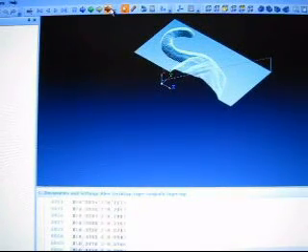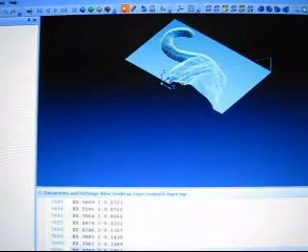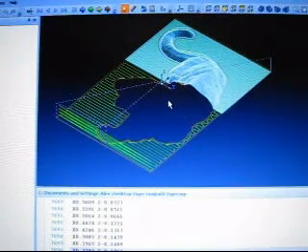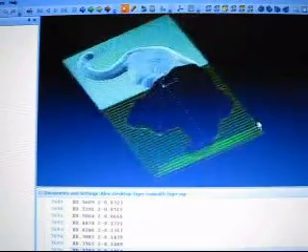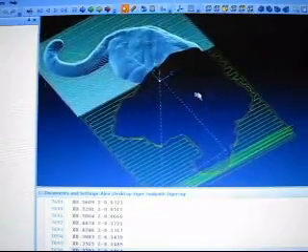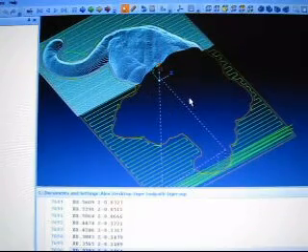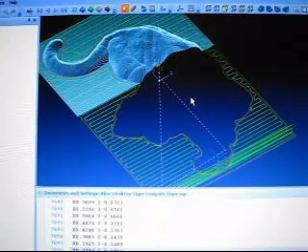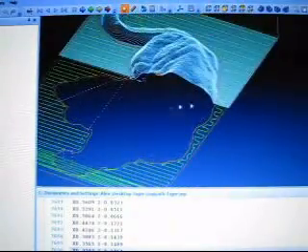We don't need all those straight areas because we're going to cut with a 1/4" end mill, a flat mill anyway, all the way around this thing, right? So it doesn't make sense to cut those straight areas with a ball tool, an 1/8" ball tool, because you're going to wind up with a whole bunch of little cusps, and it's not going to cut a perfectly flat surface anyway.